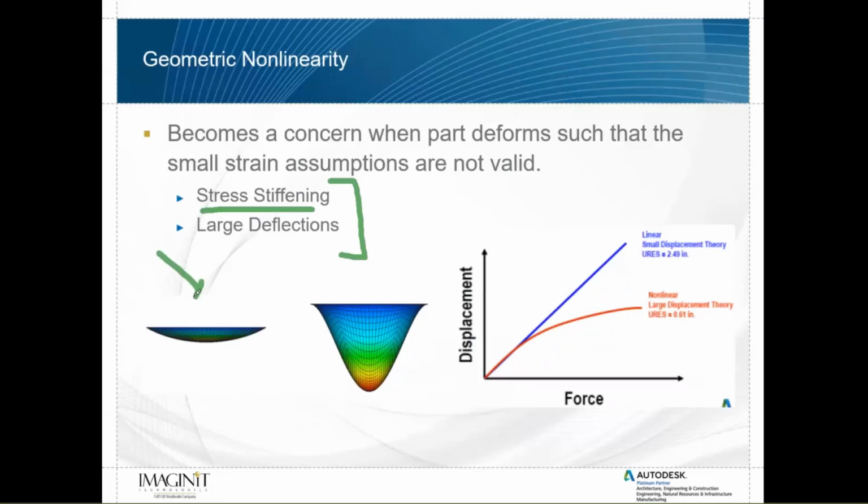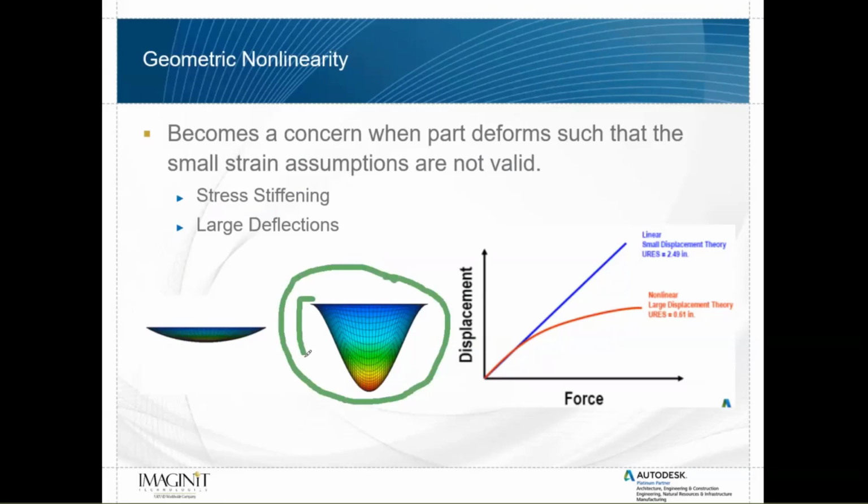So looking at this part right here, this is a simple surface, just representing like a drum membrane. If you were to run this simple surface with a point load in the middle in linear statics, you'd likely get a result that looks like this, where you have a really exaggerated amount of displacement. And I think in this case, it was something like 1,000 inches. So it starts to displace, and the element stiffness never changes. So the load path continues along the same vector. The elements displace evenly, using just the linear relationship in the material.